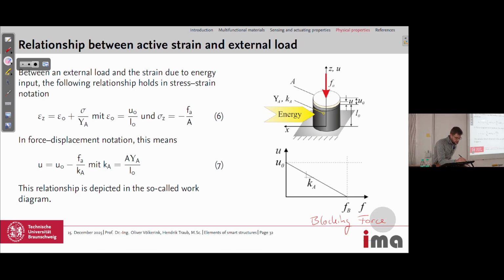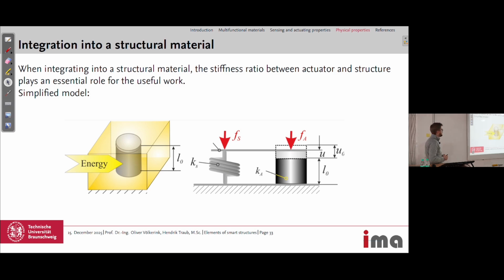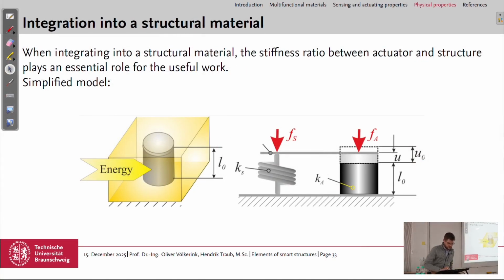Okay, then we go to the next slide. Now our model for the integration into a structural model: if you integrate this multifunctional material, a piezoceramic transducer for example, in a surrounding structure, which could be CFRP, but it's just a simple model, and supply energy, then the actuator will work against the stiffness of the structure, right?